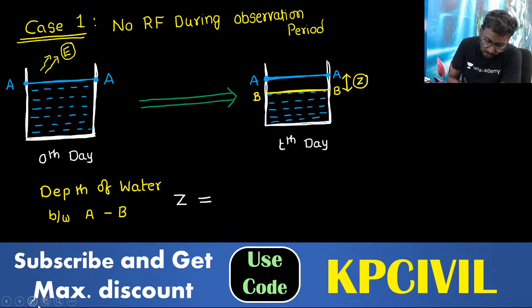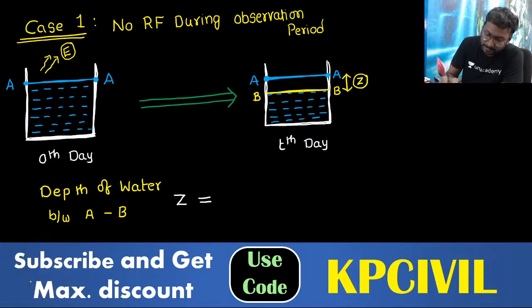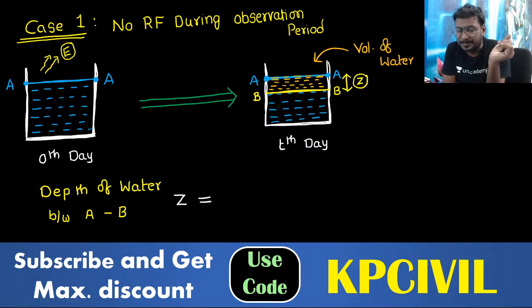So now what you are going to do here? Fill volume of water. You take some volume of water. Take, for example, you are taking a measuring jar, 5 liters of water you have taken. Slowly fill water into this. Make it rise up to A. As you have taken water through the measuring jar, you can know how much volume is filled. That empty space is there, na? In that empty space of the evaporation pan, you are filling the water.